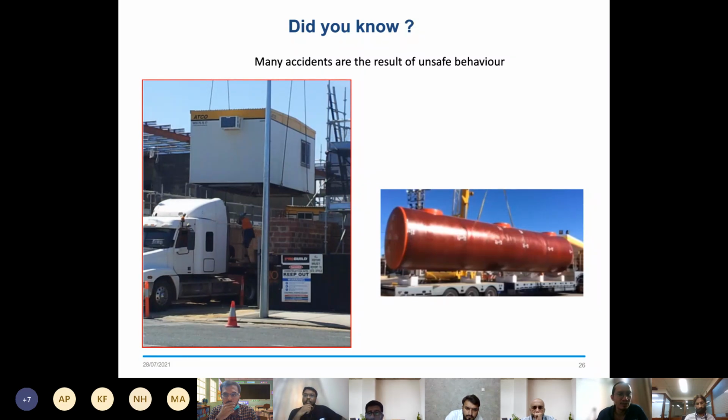Okay, thank you, Harun, for bringing up the concern. What we are essentially practicing in the local market in Malaysia now is that the tank supplier will provide the sling belt or the tank strap for lifting activity at their factory. It is precast. Everything is pre-provided by the tank supplier, whereby all working at height activity will happen at their factory. So at site, we don't have to climb up on top of the tank and install the sling bag.